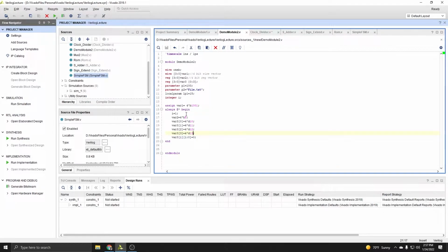The way that I like to do it often is using defined sizes. You can just do the number, but when you're working with vectors that you've defined the size already, it's a lot easier and more controllable to define the size of the constants themselves. So if you look here, all of these constants, because I created these variables of size 4-bit, all of the constants that I define here are sized 4-bit.